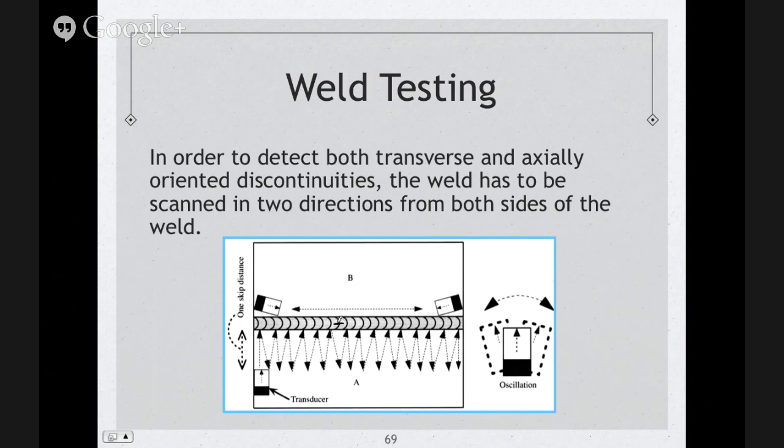So maybe discontinuities in this direction, if you're looking for transverse discontinuities. Maybe you're looking for other types of discontinuities that might be oriented in this direction, and that's why you're shooting at an angle in here, trying to get those to come back at you. And here, you scan back and forth.